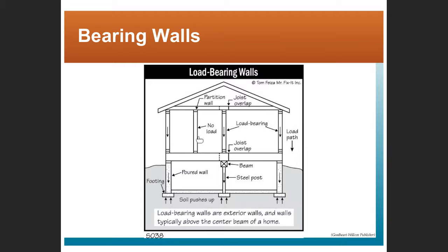So when you're doing your renovation project, you need to know what's a load bearing wall and what's not a load bearing wall. That non-load bearing wall you could demolish, you could tear out, and nothing's going to change. You tear out the load bearing wall in the middle and you could potentially have some problems.